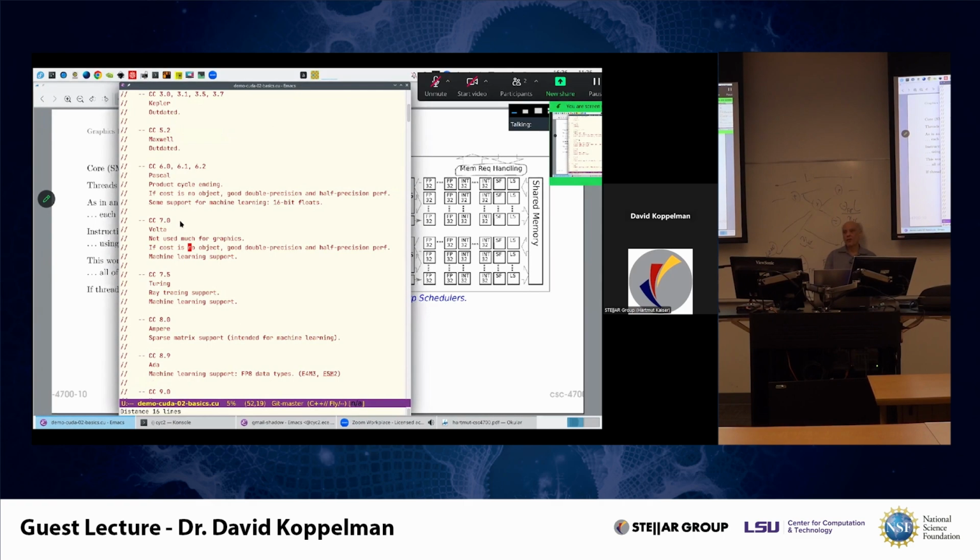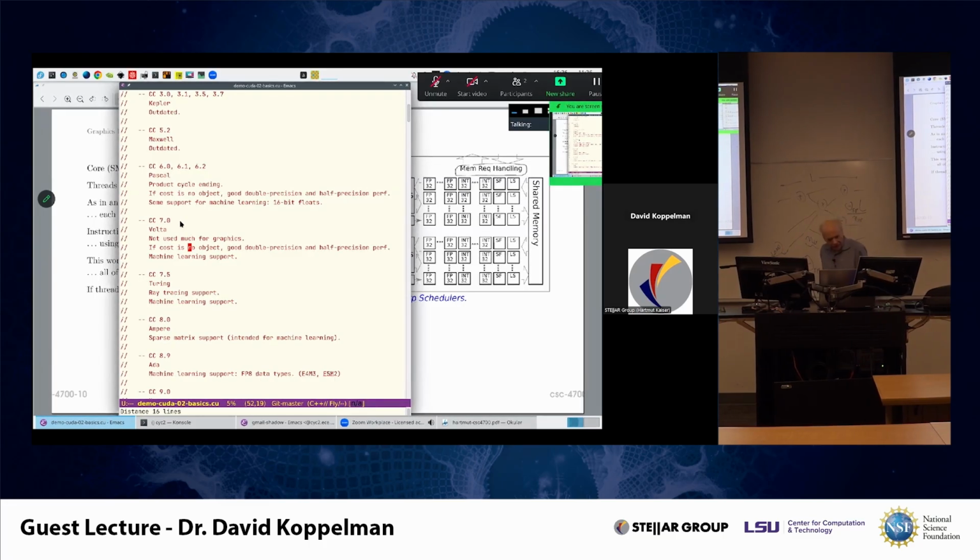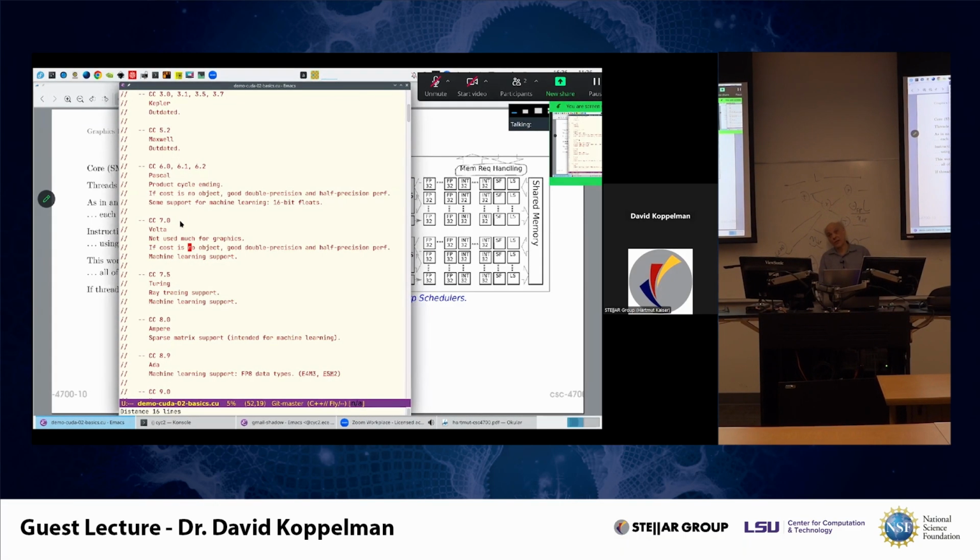So the multiplies would typically be done in a lower precision, the add in a higher precision. That lower precision started off being 16 bits, but you would add in 32-bit precision. This is done by the tensor cores. But what has happened is precision has been shrinking, going down and down.